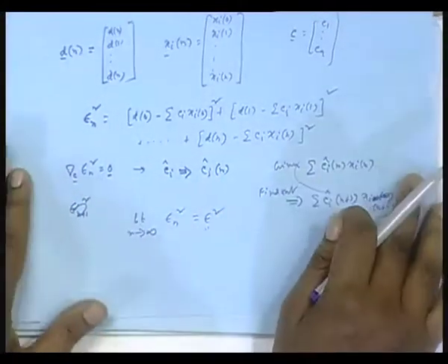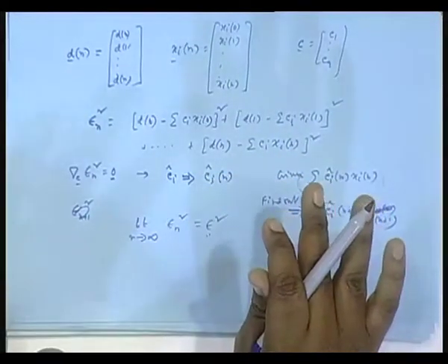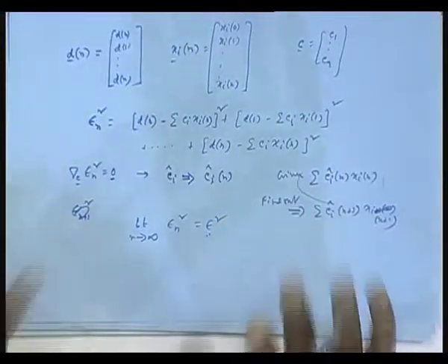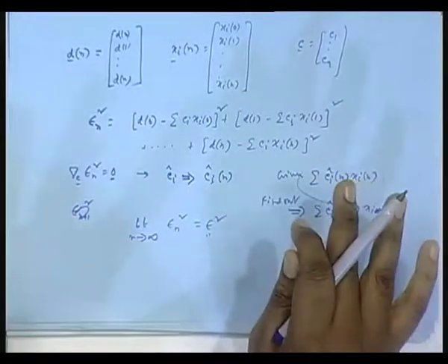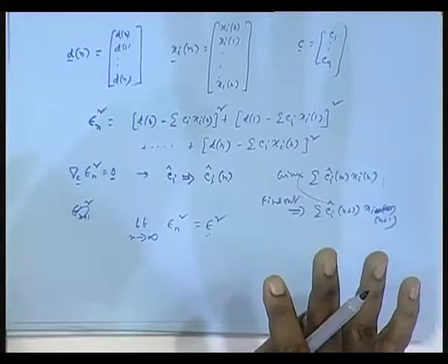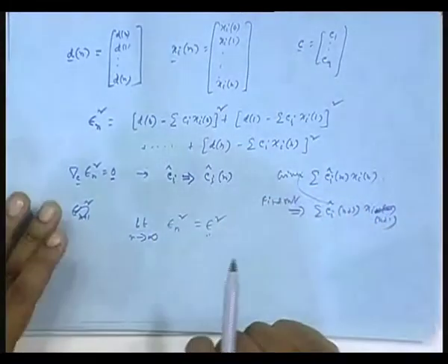And also intuitively you can see it will converge very fast, because no approximation, no search. I am not doing any search blindly and all that, isn't it? It should take much less time and also no approximation anywhere. That is why convergence is found to be faster. Okay, but the computational burden for this is much more than LMS, and also structurally it will not be so nice as you have for LMS, for VLSI implementation. Those are the things that we pay for.